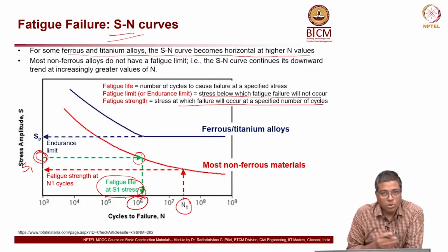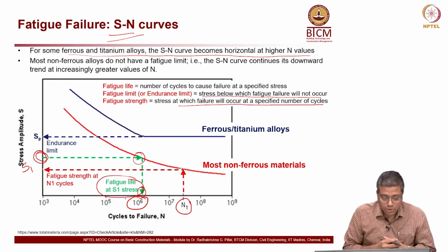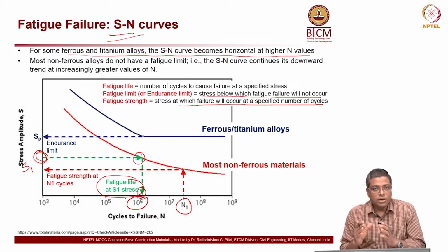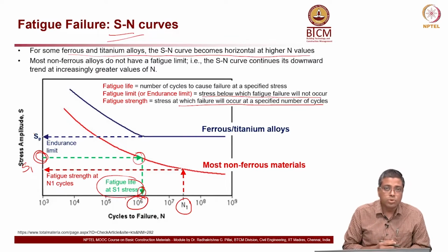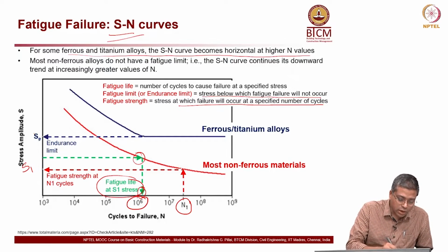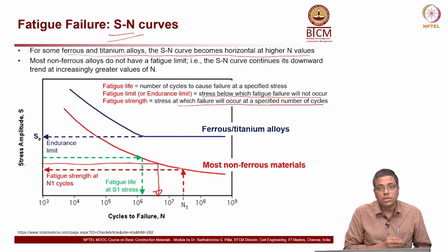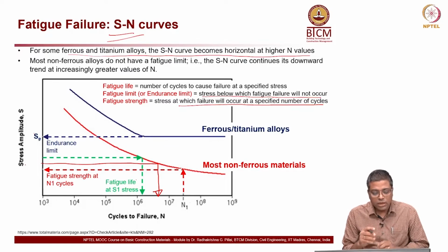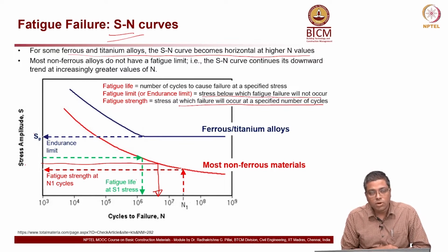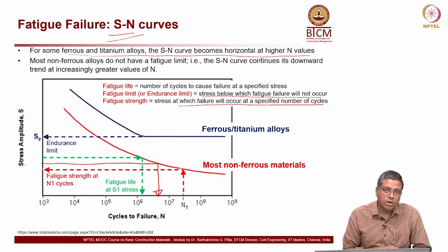So, as a person who is in charge, if the life of the structure needs to be extended, you have to reduce S1, and probably start somewhere here and then go further and make sure that it gets more life. So, this is the use of this kind of graphs. We can design the structure to resist fatigue load, and also we can design the retrofitting strategies to ensure that the structure really meets the new demand also.